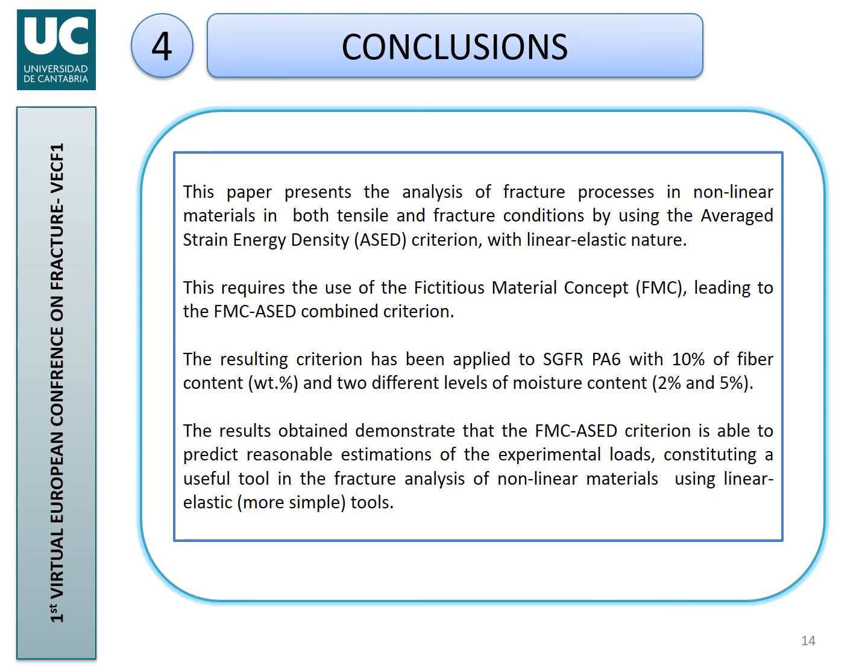So, as a conclusion, this paper has presented the application of the average strain energy density criterion to highly nonlinear materials, which requires, of course, the application of an elastic plastic correction, which is given here by the fictitious material concept.